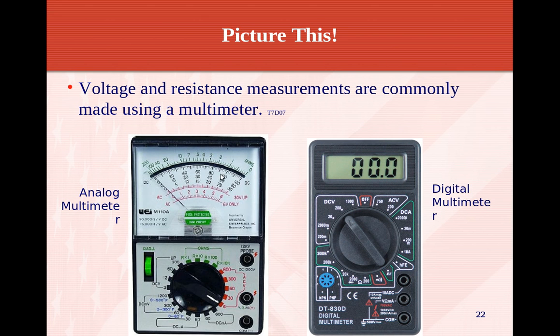This guy might be 0.1% accurate. Your multimeter is probably about 0.5% accurate. For the hobbyist, doesn't matter. I would use the digital multimeter. It's a lot more forgiving. You can hook things up backwards, and it's only going to indicate a negative symbol for voltage. If you hook up the voltage backwards, it's not going to destroy anything.